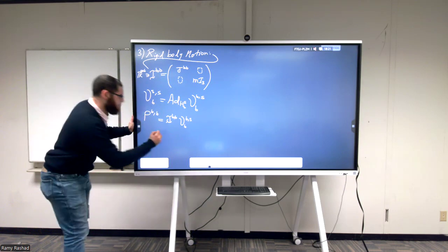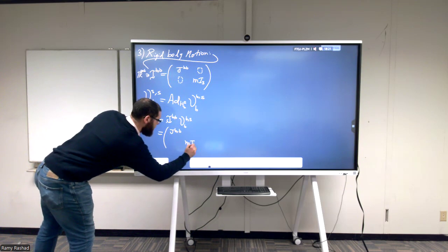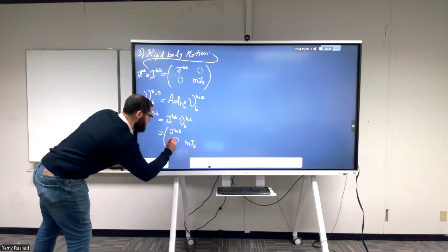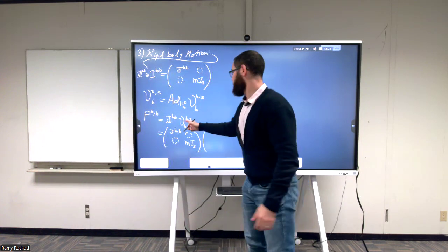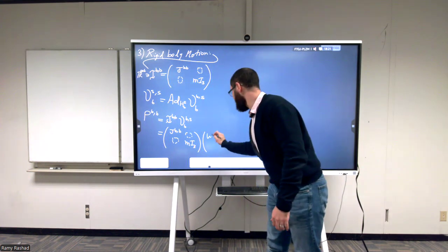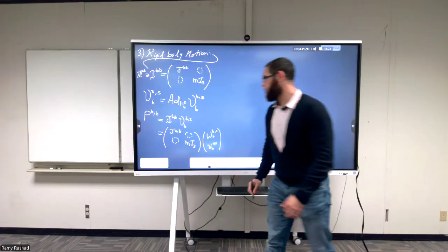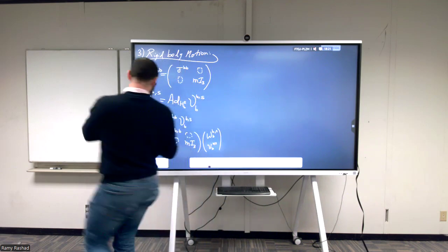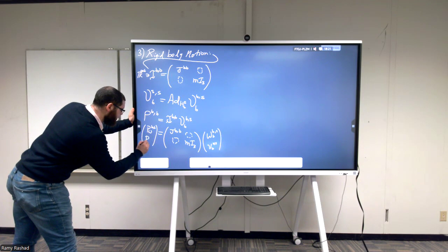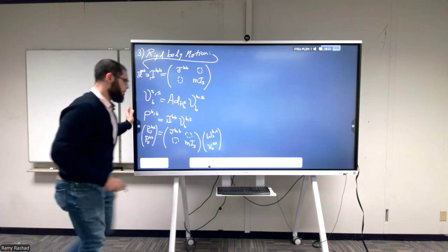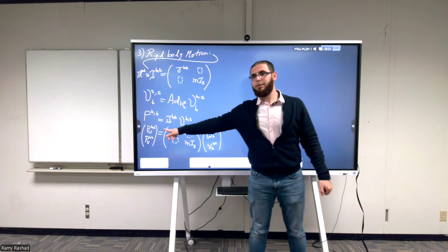Of course, we can expand it a little bit and write it down like this. So this is J, B, M, and then we have the off-diagonal terms. And this is multiplied by the twist, which had the angular velocity term in the top and the linear velocity term below. So the top part we're going to be calling the angular momentum, and the lower part the linear momentum. But when we're talking about something that's rotating and translating at the same time, the momentum changes a little bit.